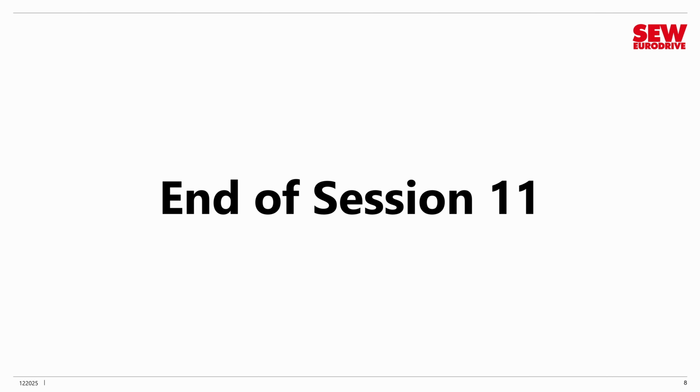Hope you found it instructive and now understand how the keypad can be used as an alternative to MOVI-C, or in some cases as an adjunct to it. It's a great tool. In our next session, we're going to tackle something a little heavier. We're going to look at a diagnostic tool built into the VFD called the scope.